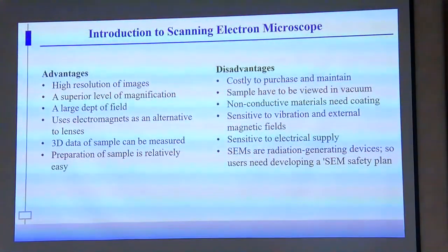But here are some disadvantages. First, for example, it's relatively costly in comparison to optical microscopy and hard to maintain. And the sample has to be viewed in a vacuum. And if we have non-conductive materials, then we need a coating of conductive material.